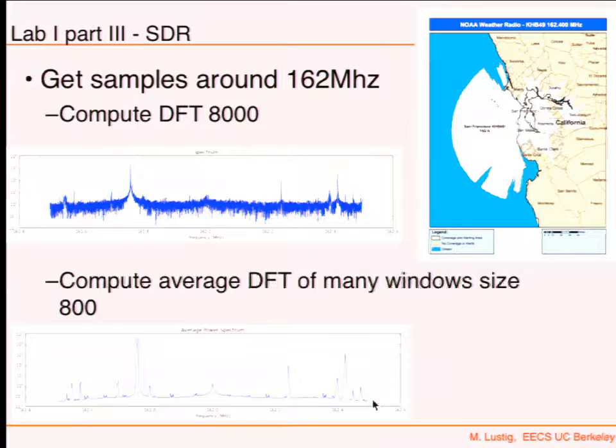The other thing that you see here is a peak at what's called a DC offset, and that's because this particular chip, if you have a DC offset on your A to D, anything that's DC that you sample, if you compute the Fourier transform, it will give you a peak in the middle. Okay, so that's one limitation of this particular design. You always see a peak here in the middle. So you want to have your station a little bit off.